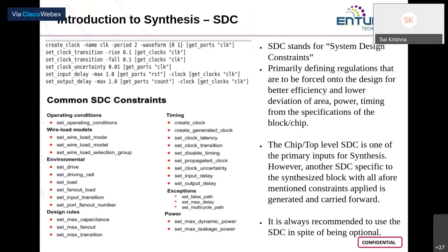Driving strength is a measure of pushing a signal outward as an output at a certain load. The higher the driving strength, the higher the load that can be driven. So obviously, the power consumption also will be high, and the cells with higher driving strength are relatively larger than the ones with lower driving strengths.